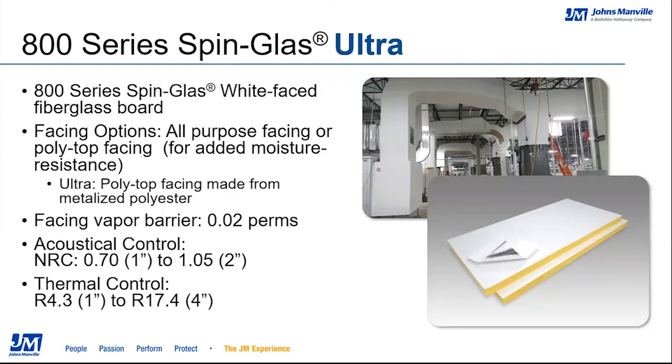It also provides strong acoustic absorption. At 1 inch thick, you have a 0.7 NRC. The thermal control range that comes with this product goes from R4.3 at 1 inch to R17.4 at 4 inches thick. That's a tremendous offering there. And for the temperature range, you can use this product in HVAC systems up to 450 degrees Fahrenheit. That polypropylene surface provides a cleanable surface once installed, and it can easily be wiped down. And this product is moisture resistant from humidity. But lastly, I have to stress, this is a paper-free product on the marketplace, and in our segment as an insulation manufacturer, we're the only ones that have this product.